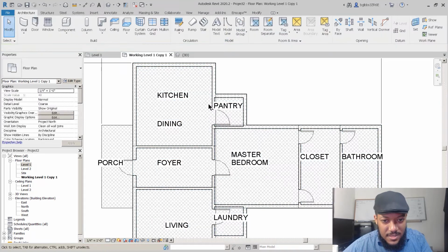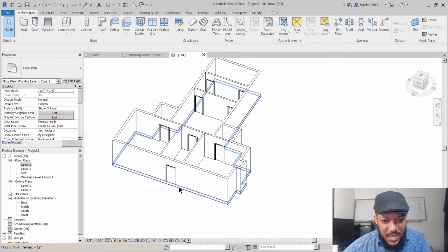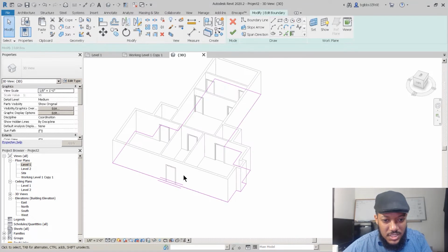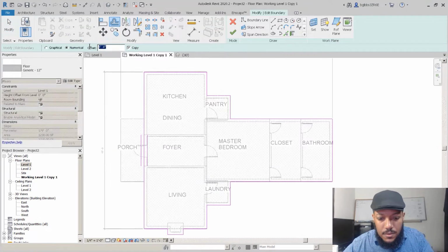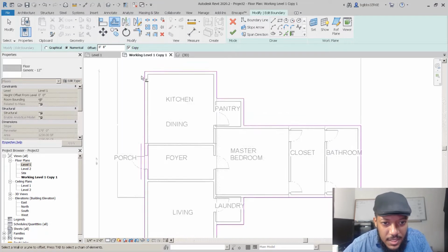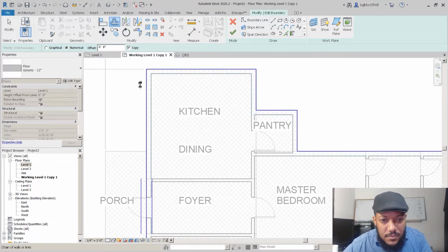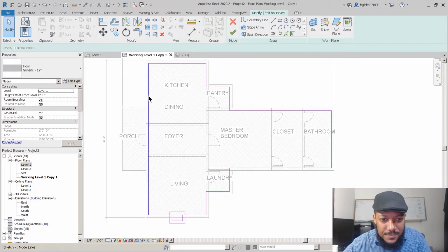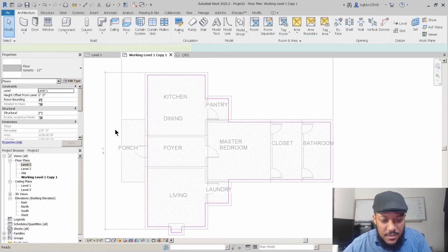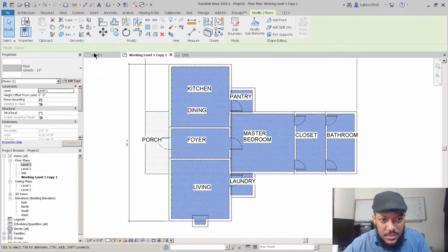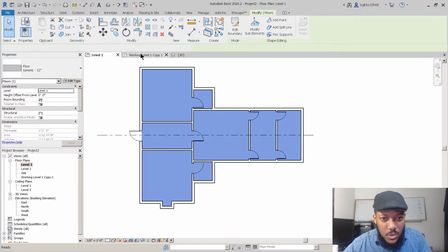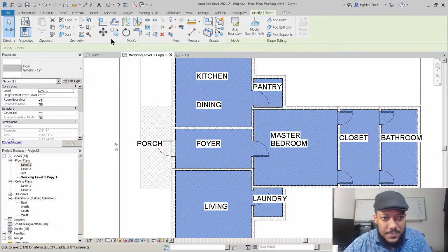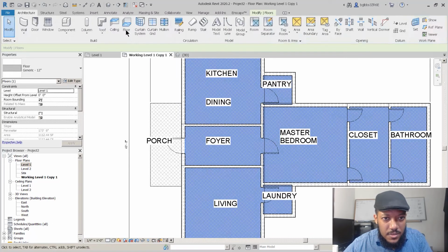And one thing about it is, if you've seen it, it was picking the outside walls, but for our construction type, we're going to probably use the inside walls. So what we're going to do is we're going to offset 8 inches this entire wall, and we'll delete the other information there. So now we have our floors, and we're looking in the working view so we can get the footprint for our porch. And we just go back to making our next floor.